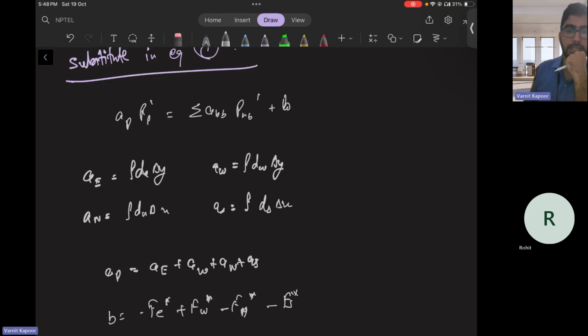Then you solve the pressure correction, correct the pressures, correct the flow rates. Then correct the cell pressure using some under relaxation if you want. Then correct the cell velocities, solve additional scalar transport equations, then check for convergence, and if it is not converged, then go to step 2.